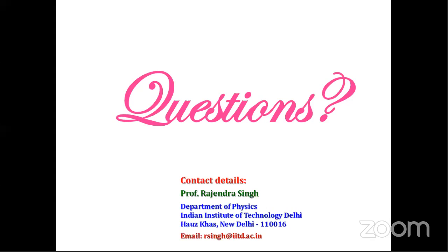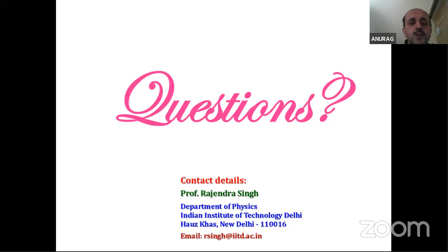Raja Songdan asked if it is possible to measure resistivity of ferroelectric thin films by the 4-probe method. Yeah, the 4-probe method is very versatile. You can measure the resistivity of any kind of sample. But as I have told you, you have to know a little bit what is the resistivity of your sample. And the second thing is, accordingly, if its resistivity is very high, then you cannot use exactly the setup which you are using for semiconductor measurements.